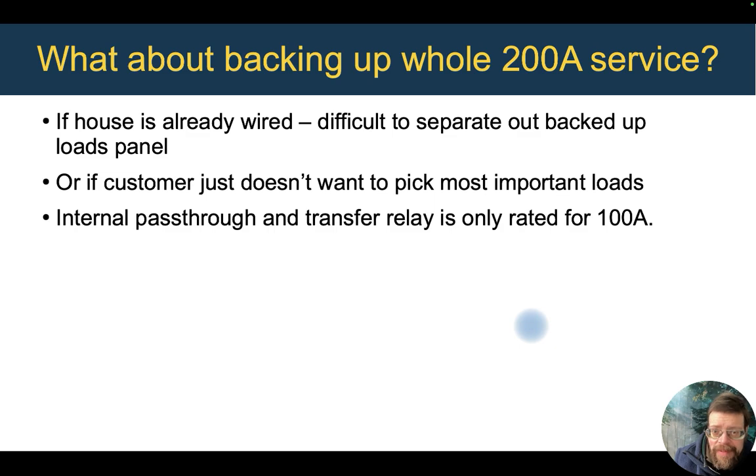What about backing up the entire 200 amp service? This is something that more and more we're asked about. If the house is already wired, it might be difficult to separate out the backed up loads. Maybe it's in a separate part of the house, not on the exterior, not in the garage where we have access to our service.